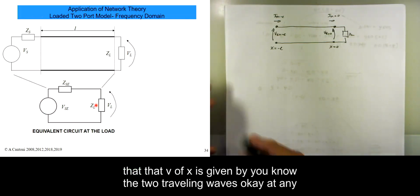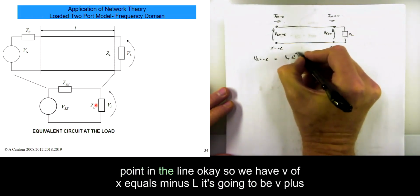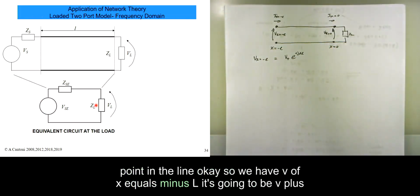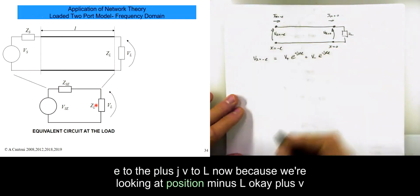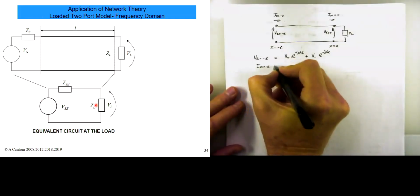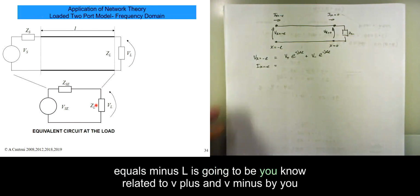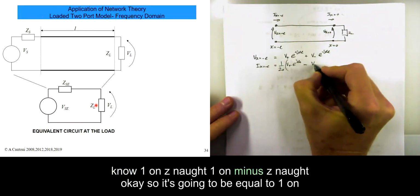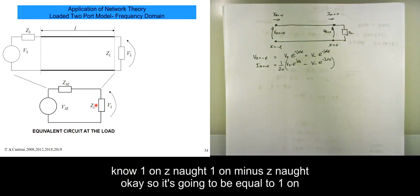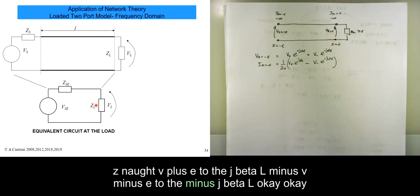And again, we know that V of x is given by the two traveling waves at any point in the line. So V of x equals minus L is going to be V plus e to the plus j beta L now, because we're looking at position minus L, plus V minus e to the minus j beta L. And I of x equals minus L is related to V plus and V minus by 1 on Z0 or 1 on minus Z0. So it's going to be equal to 1 on Z0, V plus e to the j beta L, minus V minus e to the minus j beta L.